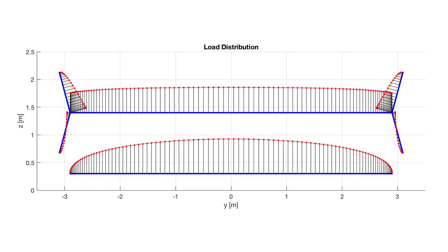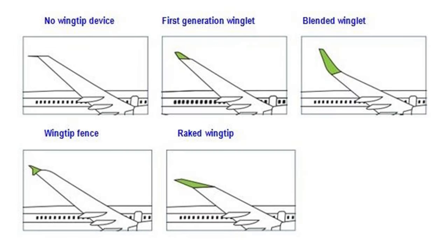Unlike a simple end plate or fence, a winglet carries an aerodynamic load. Its purpose is to create a flow field that interacts with the main wing's flow field in a manner that decreases the wing's overall span-wise flow. Essentially, the span-wise induced velocities from the winglet itself counteract and cancel those produced by the main wing, if the winglet is designed properly. This is an elegant solution that cleverly uses aerodynamic loading to accomplish the same reduction in main wing span-wise flow by using significantly less wetted area than the equivalent flat and excessive end plate.